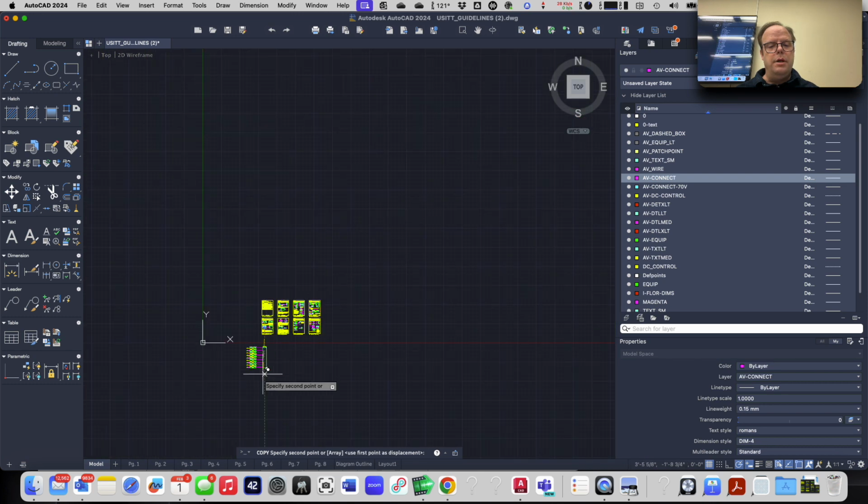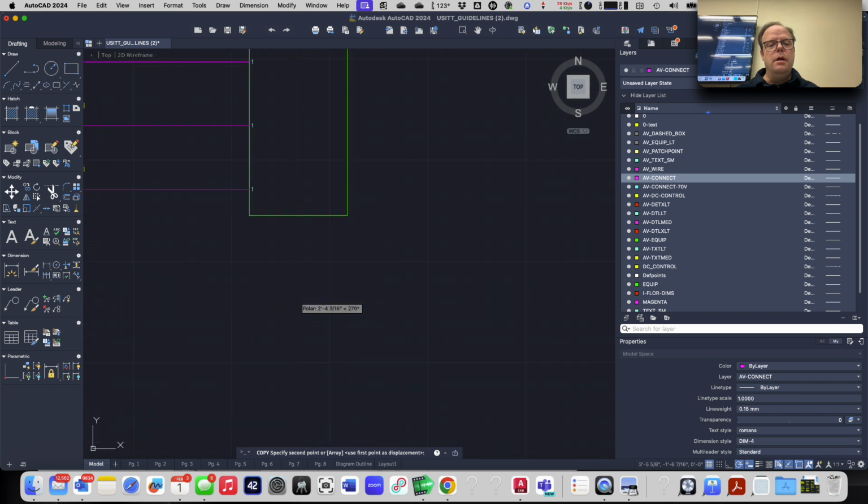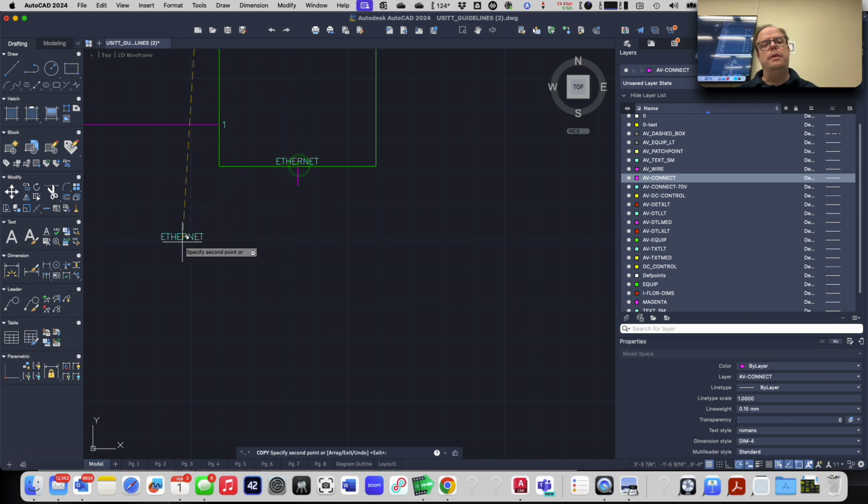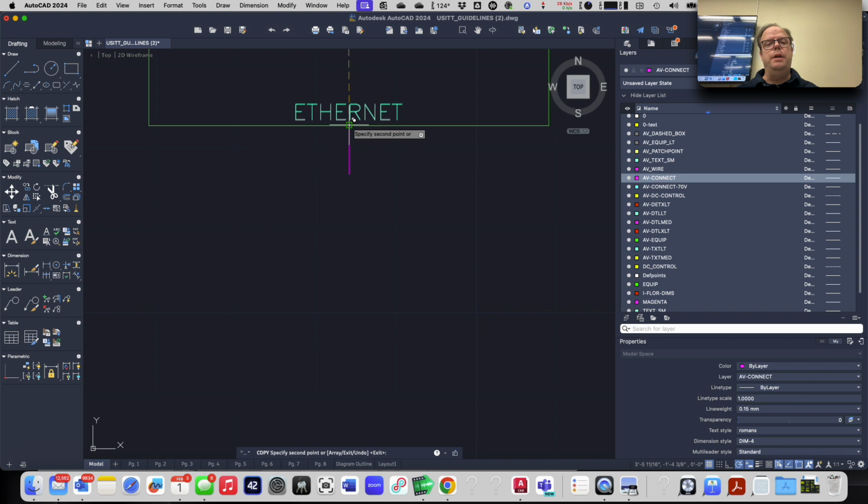And now I'll go down here and I will snap it to that same midpoint of this bottom thing and click. And there it is. Now, I also need another one. So I'm going to now do a snap and track to the left here until I get a good horizontal spacing. And then I'll click. And now I'll be done with that command.